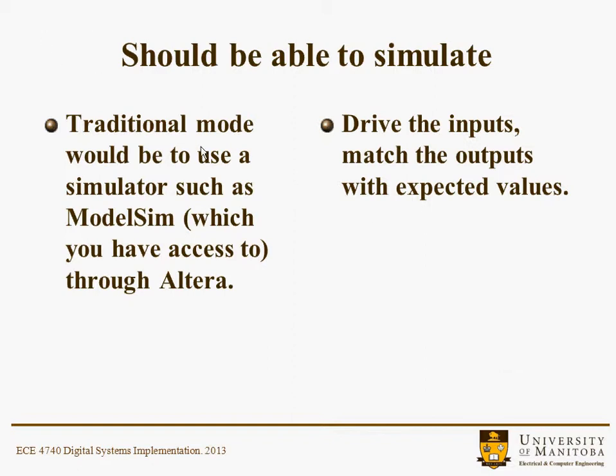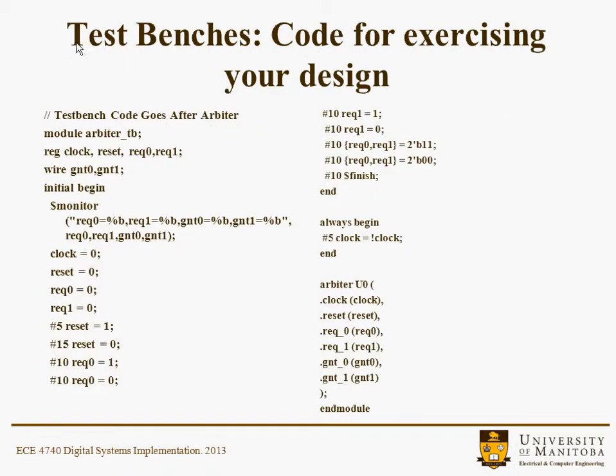The traditional mode would use a simulator such as ModelSim, which you have access to through Altera. You drive the inputs, you set them to what you want them to be, watch what the outputs are, and see that they're as what you'd expect. More recently, people spend a lot more time writing test benches, and basically it's code for exercising your design. So it makes your life a lot easier. Here's where the code would go for the arbiter, and then this test bench code. So it's another module. It's an arbiter test bench.